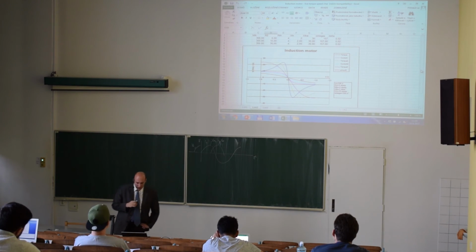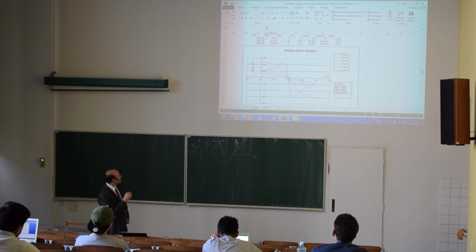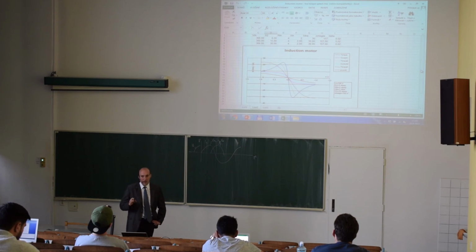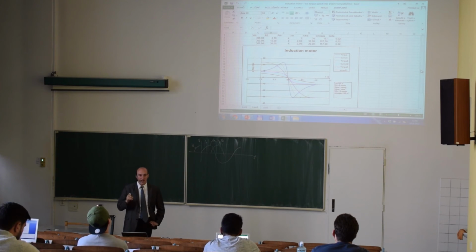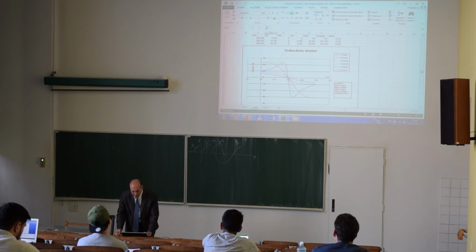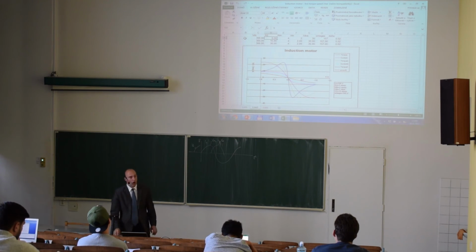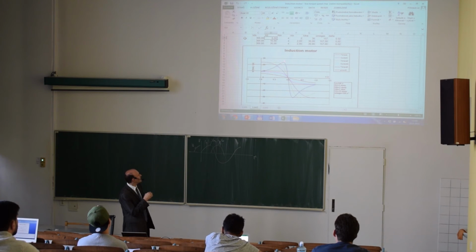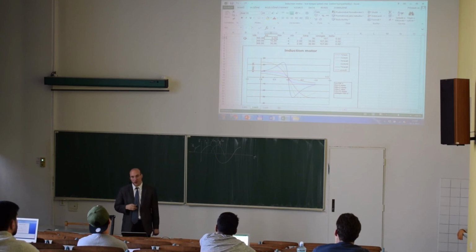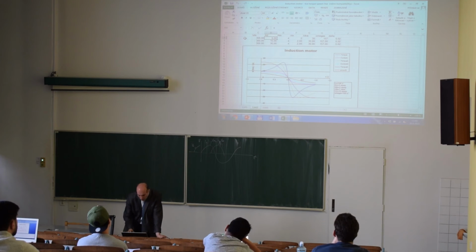The torque speed characteristic depends strongly on the rotor resistance here. So R2, as represented in the equivalent circuit diagram, is the resistance of the rotor, and we will see it has a very big influence on the torque speed characteristic. So here I have some values. Let's say 6 ohms will give me this type of torque speed characteristic. What will happen, for example, if I choose 3?